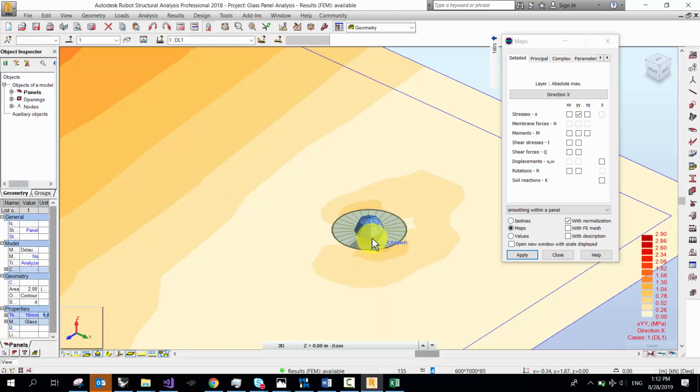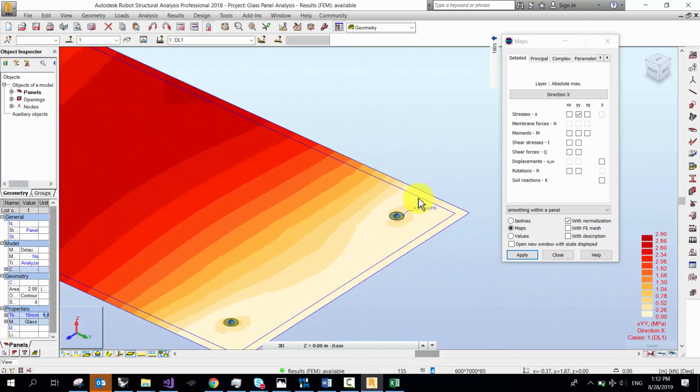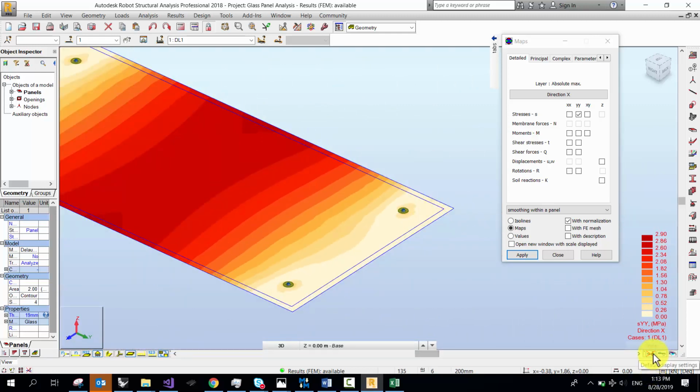This also transfers the moment. It does not. No, it does not. But at the full point, usually we only restrain the three directions at one point, and at the other point we release the lateral, so that it doesn't have the ability to develop catenary reaction or something. That's very good. And the lateral will only be at the top.